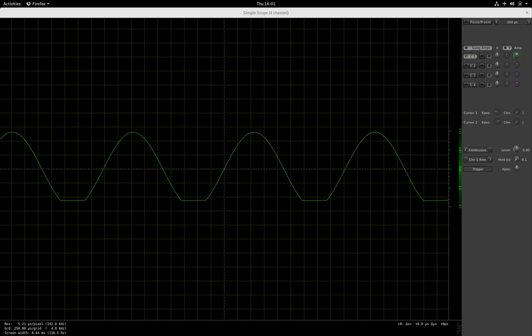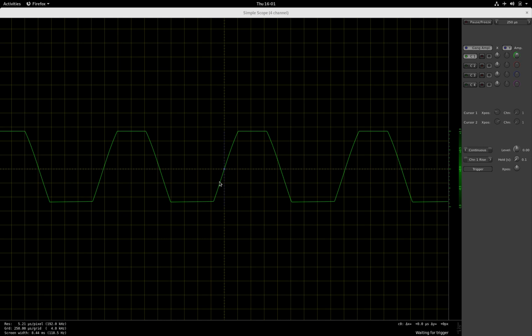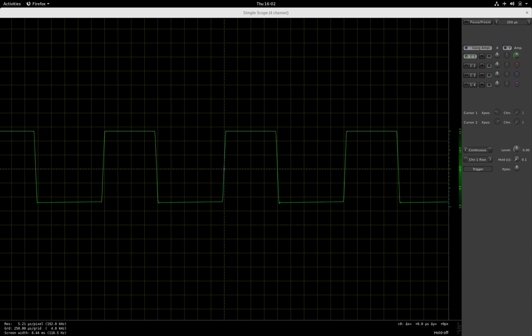Now we also have a gain control on our fuzz unit, and if we increase the gain, as with our other units, the slope of the signal through the origin will increase, and the signal will get clipped both on the positive and on the negative side. And the more we increase the gain, the steeper the slope through the origin, and the more clipped it will be.